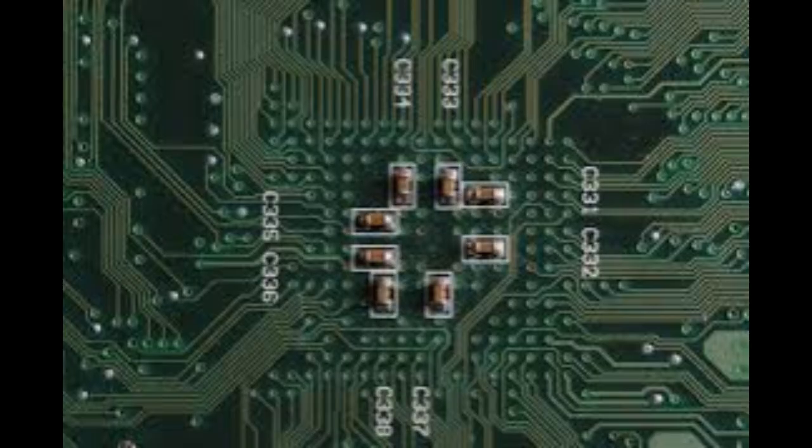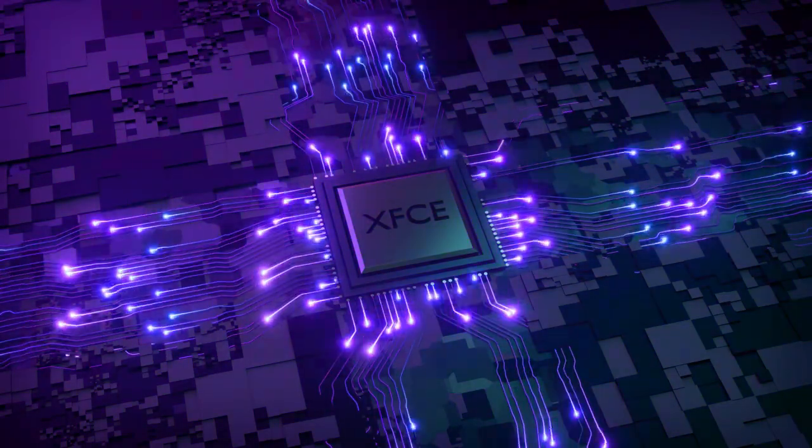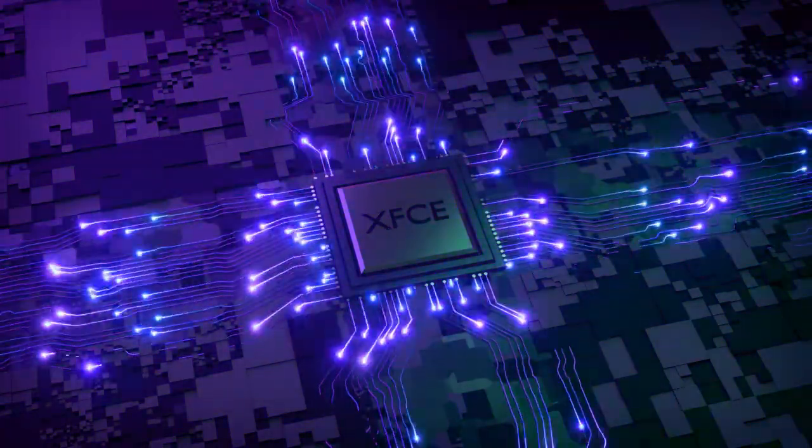Ultraviolet light projects the circuit pattern. The exposed areas are chemically removed, and then materials like copper and insulators are deposited. This process repeats dozens of times, building layer upon layer of microscopic circuitry. Eventually, the wafer contains fully formed processors. It's then cut apart, tested, and packaged into the chips that get installed into computers.